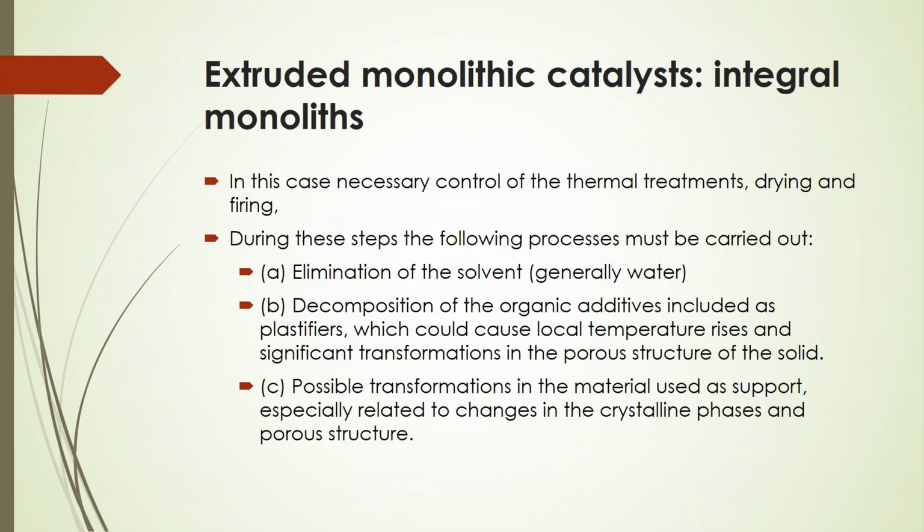In the case of integral monoliths, some necessary control of the thermal treatments should be done, as well as drying and firing. During these steps, the following processes must be carried out: elimination of the solvent, generally water, and decomposition of the inorganic additives that may be included as plasticizers, which may cause local temperature rises and also significant transformations in the porous structure of the solid.